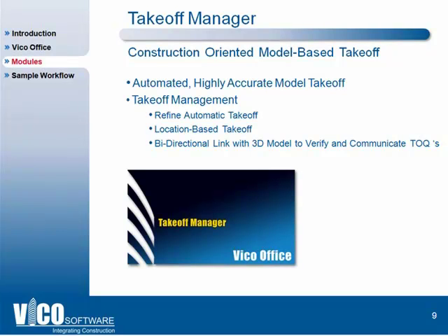After the initial takeoff, Takeoff Manager will allow you to regroup the takeoff information. So if there are elements that you think belong to a different group or to a new group of takeoff items, you can reassign them with a reassigning functionality, which we will demonstrate today. Of course, because we have the geometry inside the Vico Office platform, all your quantities can be visualized as soon as you click on them. So if you select a takeoff item, the associated elements will be highlighted in the 3D model.